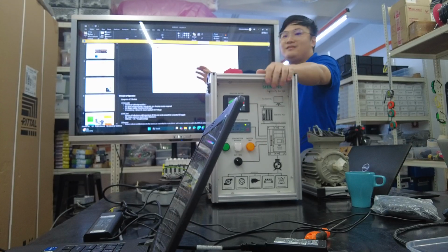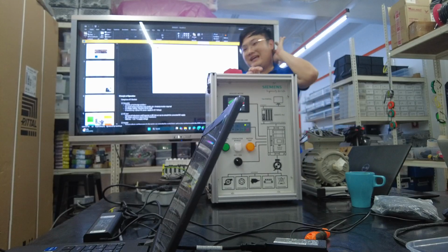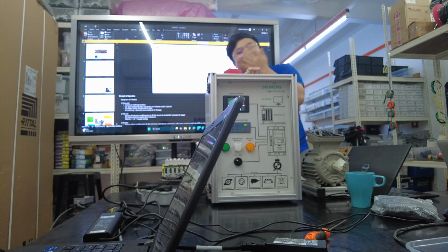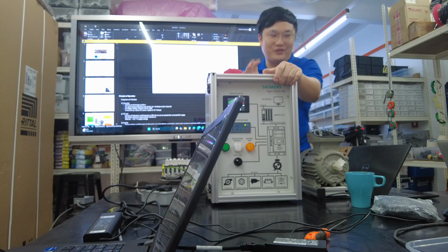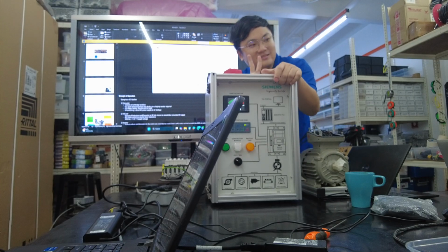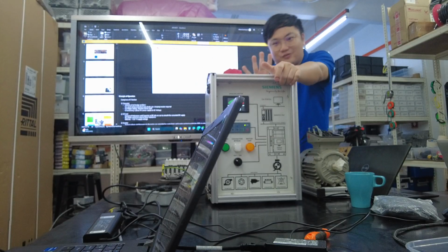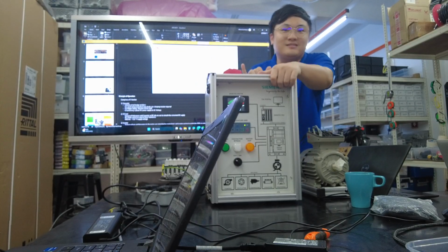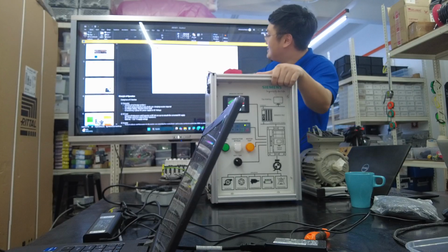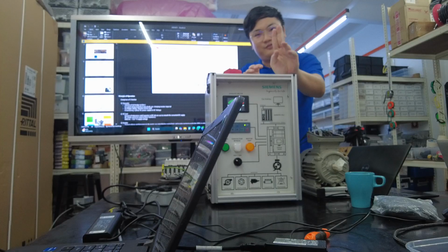So inverter usually 100 milliseconds. No, speed. Switching speed, in hertz. The frequency switching speed. How many hertz per second? For your concept, a low-end inverter is about 2000 hertz, 2 kilohertz. For a normal Siemens inverter, we talk about 4000 to 16,000 hertz. Imagine the IGBT switching 4,000 times per second. With a low-end drive, 2 kilohertz.